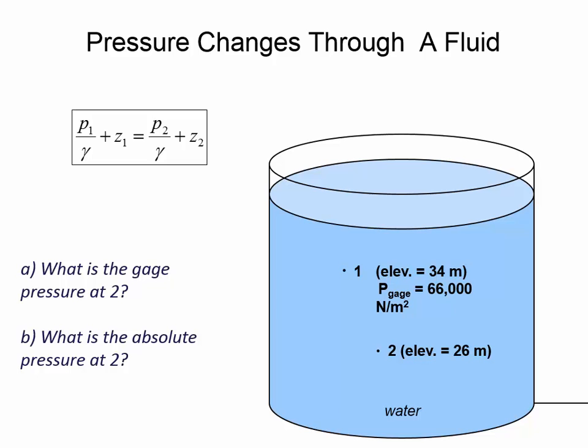And that would be the unit weight of water at a little bit cooler than room temperature. Most of the water that flows through pipe networks is at about 55 Fahrenheit, in that range, because ground temperatures are cooler than room temperatures. And so I think maybe 9810 would correspond to the unit weight of water that you'd see going through a municipal pipe network. Closer anyway. Thank you for asking that.